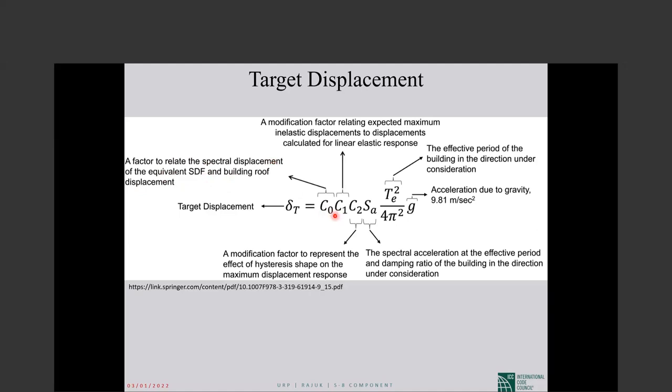But we also had it in the table form that depends on the building. I forgot to say how we recognize that a building is shear type or bending type. If we have a building, we apply the lateral load to it and look at the drifts in the story.